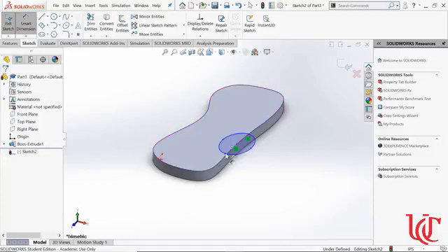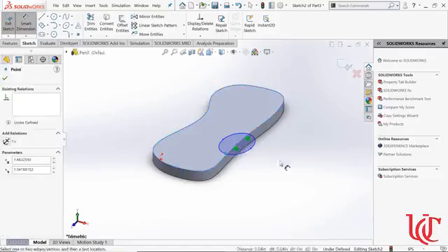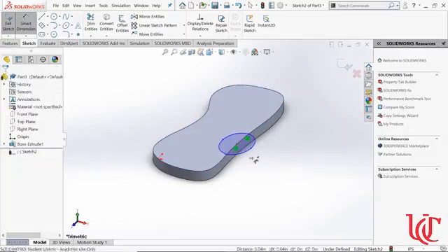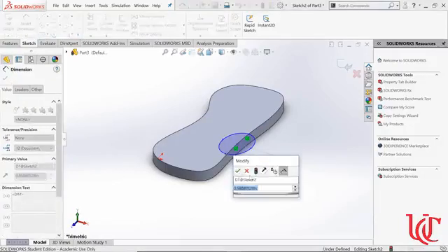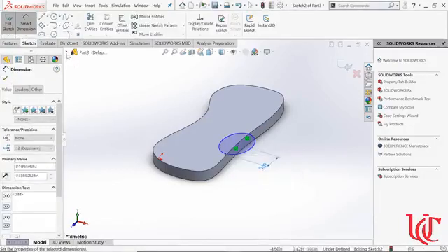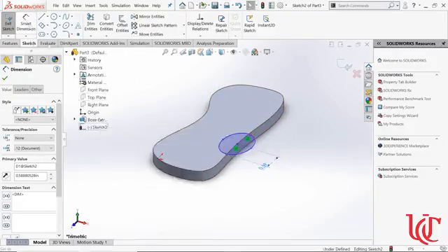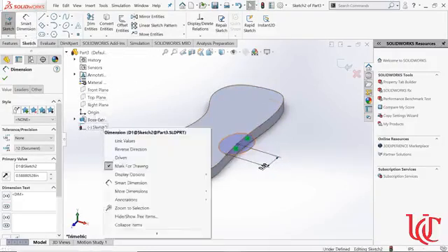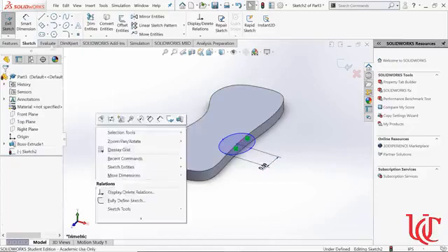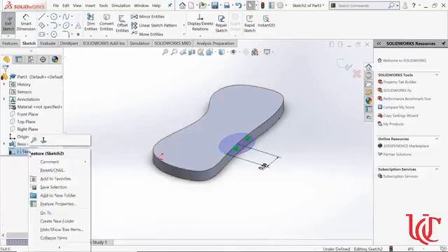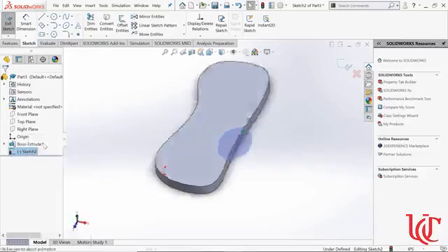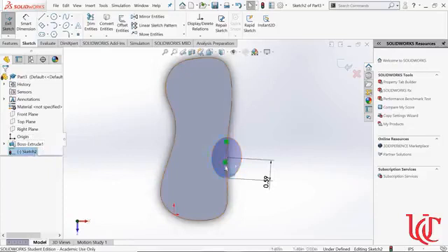And I'm going to smart dimension my ellipse. So from here, oops, to here, needs to be some distance. If you don't like that you're in an angled view from this, you can always, from your feature manager, select that arrow down, find the sketch you're in, get out of smart dimension, find the sketch you're in, right click on it. Oh, goodness, I'm not having good luck with that today. Sketch you're in, right click on it and say normal to. Now I'm looking straight onto that sketch.